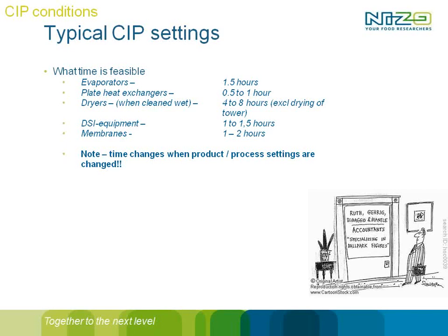Direct steam injection, DSI equipment, 1 to 1.5 hours, and membranes depend a bit on the configuration again. They are a bit more difficult to clean and also less resistant against all types of aggressive chemicals. So it depends on the type of cleaning component you use, but 1 to 2 hours should be feasible. What agent should be used?